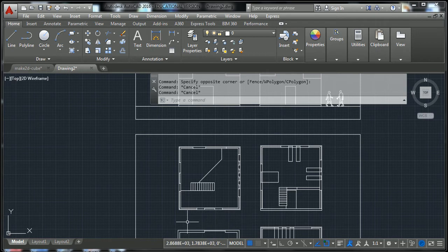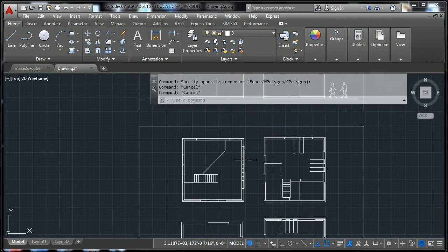That really occurs because Rhino is basically a hollow modeler. It's not really a solid modeler, so whatever's inside that wall is hollow, and you're seeing what's below. And we could prove that by looking at the Rhino model itself.